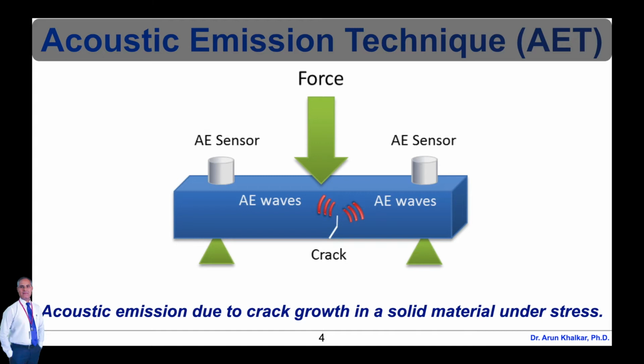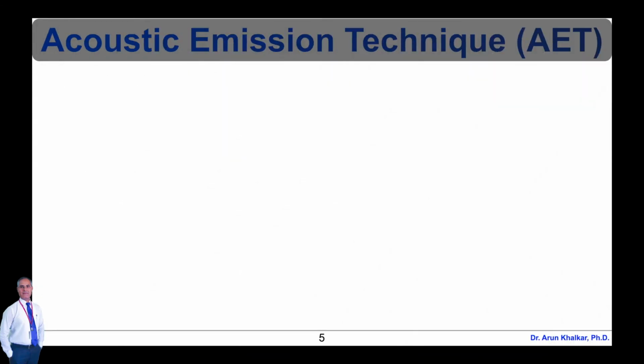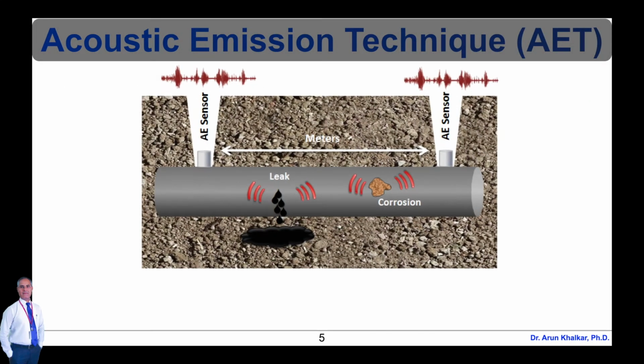Sources generating acoustic emission in different materials are unique. For example, in metals, primary macroscopic sources are crack jumps, processes related to plastic deformation development and fracturing, and debonding of inclusions. Quantitative and qualitative characteristics of acoustic emission waves generated by sources of different nature depend directly on material properties and environmental factors. Piping inspection is another common application.